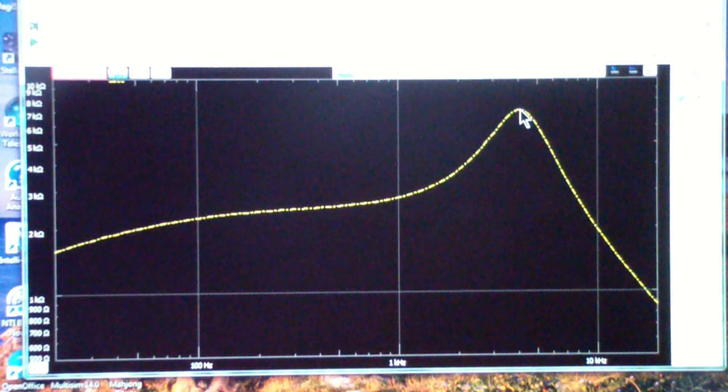Then you get a peak that peaks to about 8,000 ohms at about 5 kilohertz, and then is back to the 2.5K just before about 9 kilohertz. So what you have here is a decent radio speaker, which is what this unit was designed to do. It's a signal tracer for tracing radios of the 1940s and 50s. So this is a perfectly adequate output transformer where the maximum frequency response of a radio was around 5 kilohertz, which would be about here.